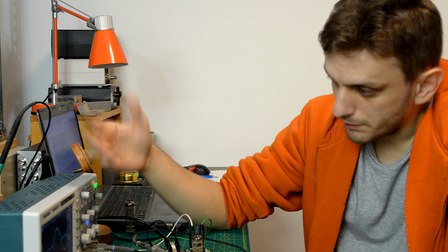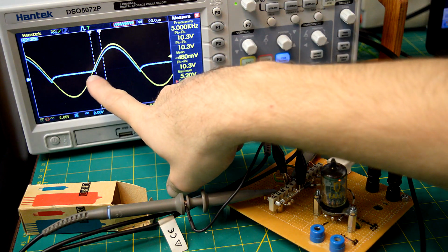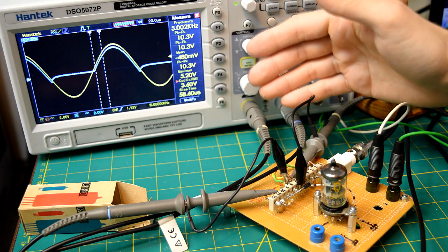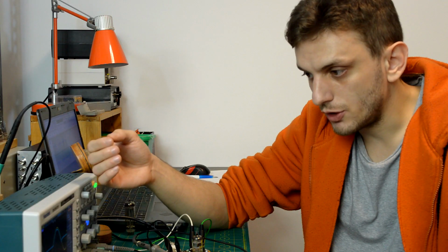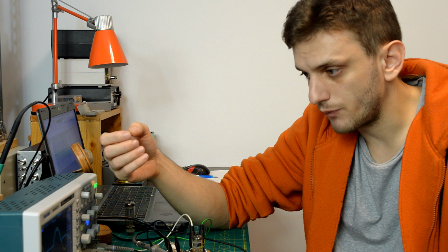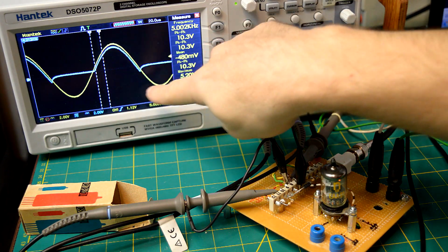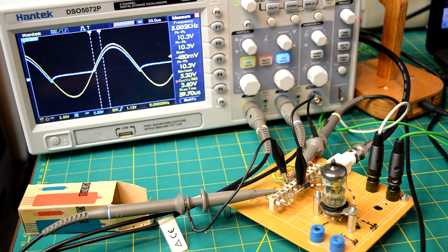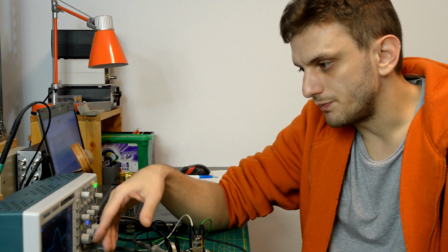We can see that when the voltage first turns positive, there's a bit of a delay between the input and the output voltage, and that is caused by the minimum voltage needed to turn on the semiconductor diode, roughly 0.6 volts for silicon diodes. Then at the end, when the diode stops conducting, we see this little glitch going on, which is basically reverse recovery. The silicon diode doesn't stop conducting all of a sudden when the voltage turns negative. There's a bit of a delay.